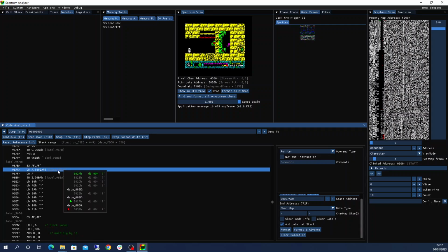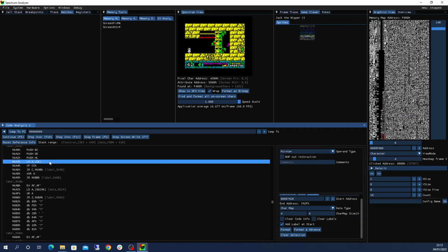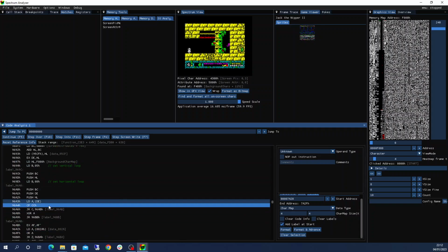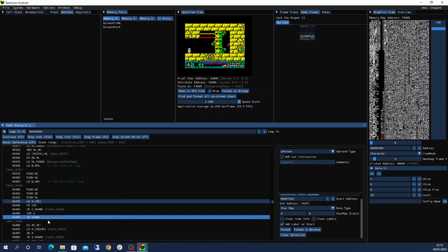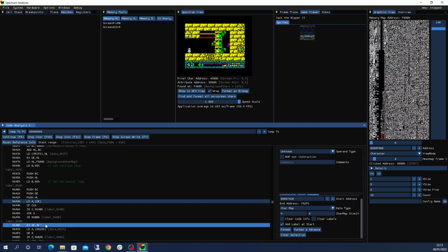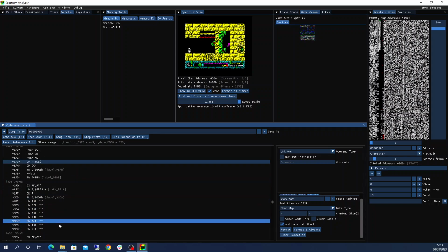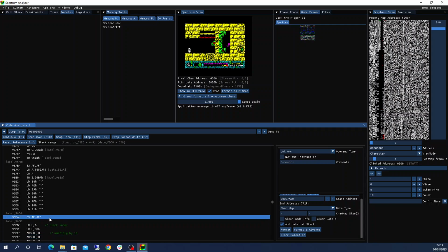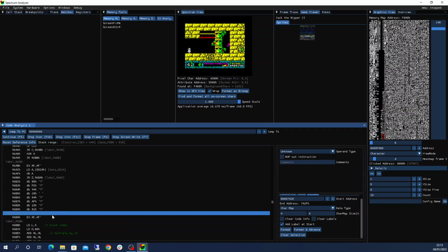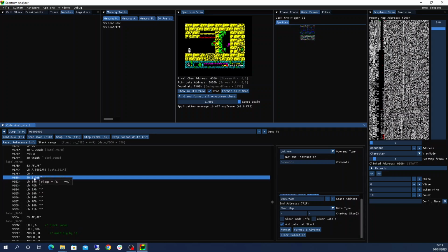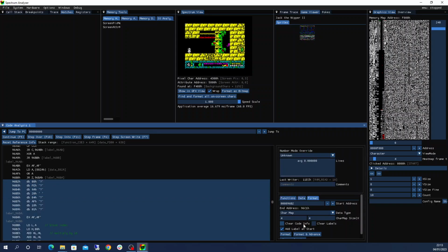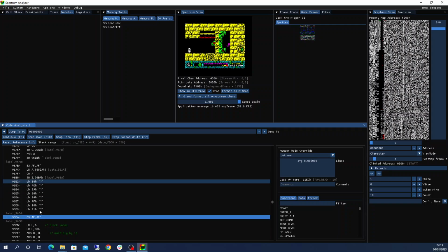That's reading some value there. Okay, that looks like it. So it does some checks there. It backs it up in the shadow register there. Presumably it restores it there. Then it pulls it in. Okay, and we've got some logic here. Now one thing is that code that doesn't get run doesn't get marked as code. But when we look at this, we can see it's a JR Z. So every time this is run, the zero flag's always been set. But there is code there that can run if it's not set, it just hasn't been run yet.